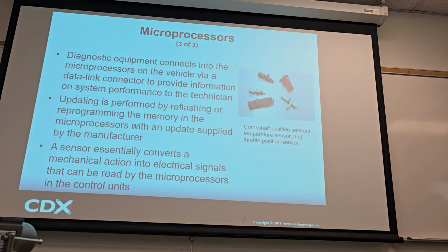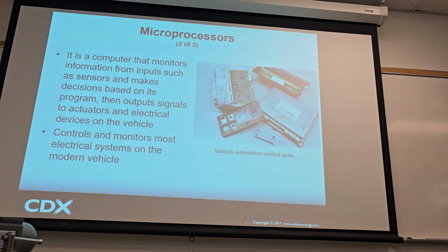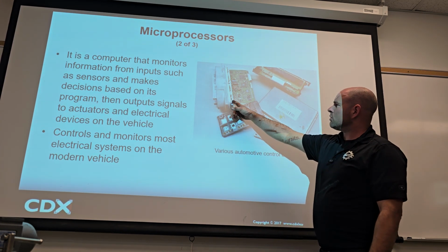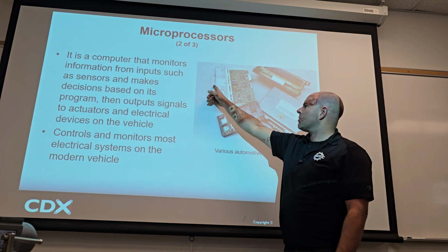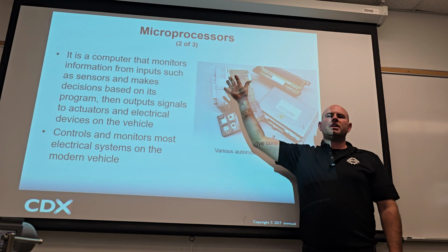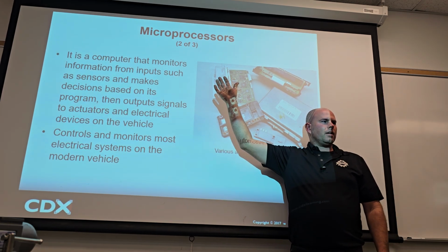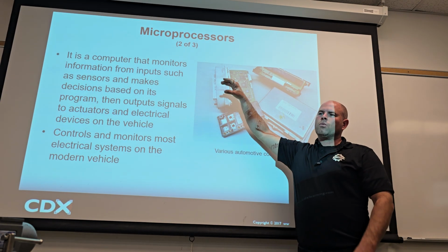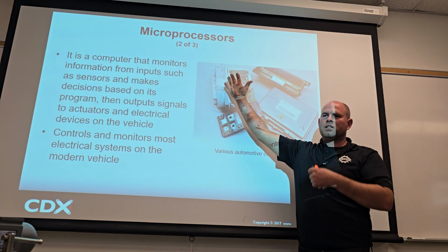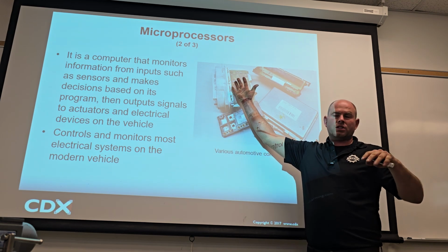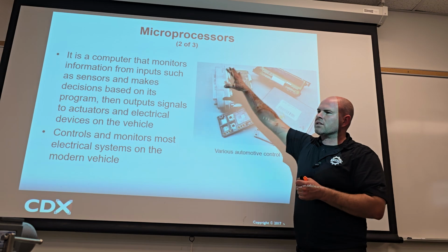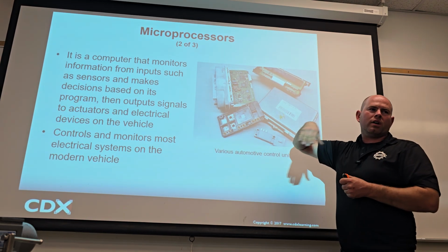One thing I'd like to say: on a car, if you take one of these out and plug a new one in, this one probably is, yeah. It looks like it. I remember the blue writing. So if you take this out and plug a new one in on a modern car, it ain't gonna work. This has to be programmed to the vehicle with the correct options, and a lot of times the VIN number, and a lot of times if it's new, it comes with no software in it at all. The hardware is there, but the software is not. So when you get into replacing stuff like this, it gets into a lot of programming.